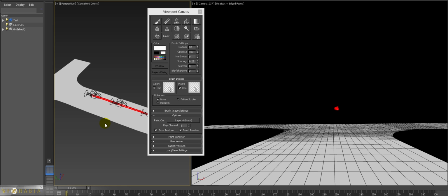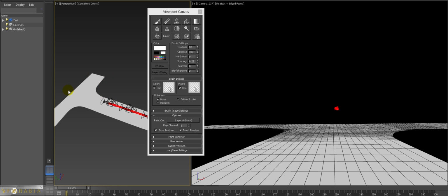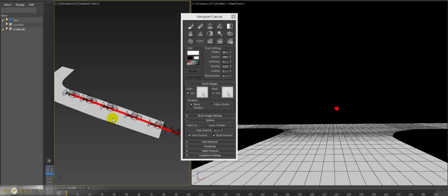And another thing I wanted to mention, it's not always advisable after you finish mapping your object to do rendered texture, because rendered texture has some limitation of the output, especially if your object is big. For example, like this road, we have a couple of high definition images involved in the final map for this. So you have more than 8,000 pixels here. So I don't think rendered texture is gonna help you in big scene situations. So just be careful. That's it for this tool.